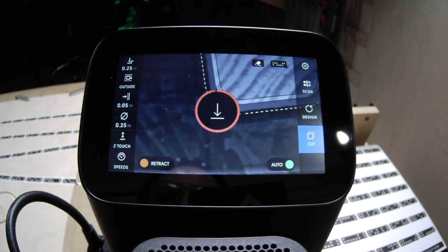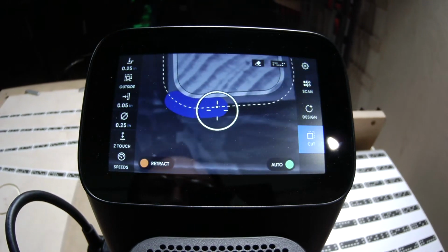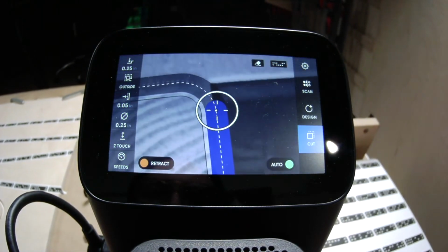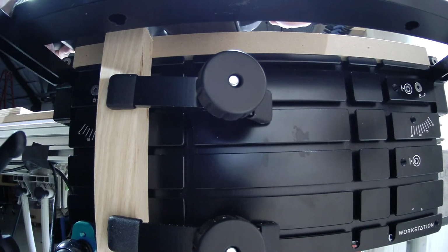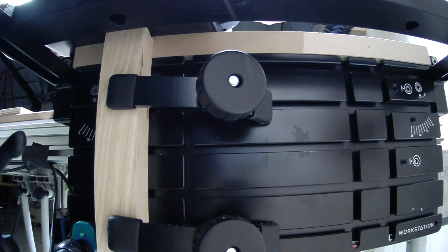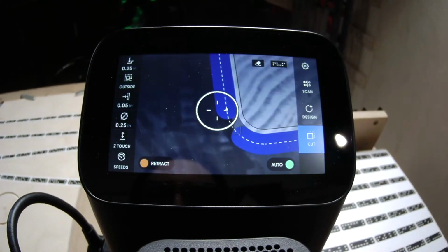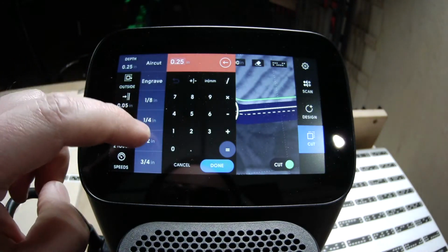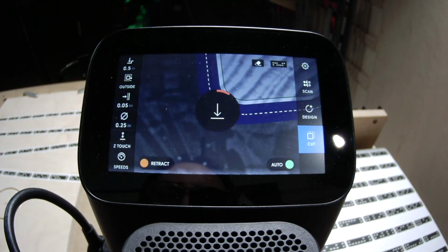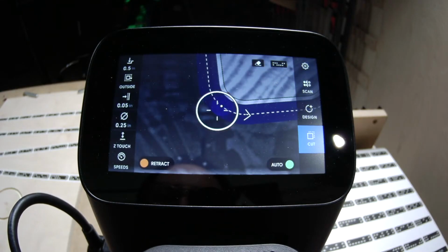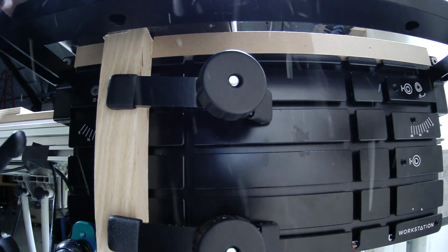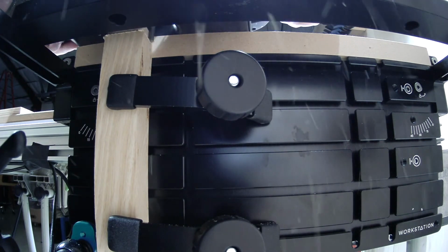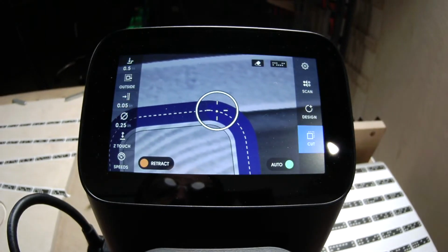And when you're starting out new, I typically like to start from the same spot every time. So I typically, like Noah, start in the bottom left of whatever shape I'm at. That way your routine really builds that kind of ordinary action. And so, we did our first pass, we retract, we go down another 1/4 inch and plunge again. So now we're down at 1/2 inch, and you can see the bit here starting to remove material in the bottom. Same thing, we're just going slow. Really a standard speed.